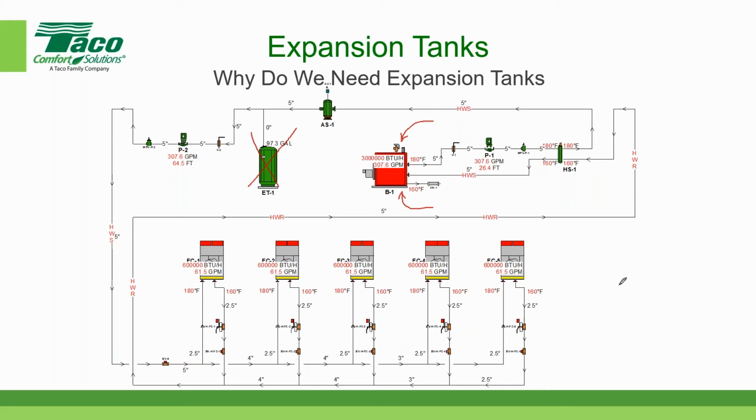The second reason, which is also extremely important, is that the expansion tank needs to be connected. In this case, it's connected to the suction side of the pump. Here's the suction side of the pump over here. And this is known as the point of no pressure change.